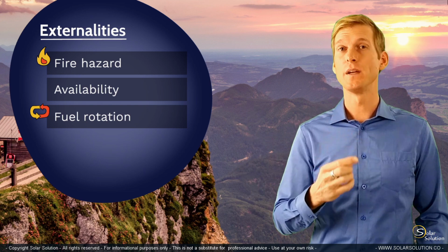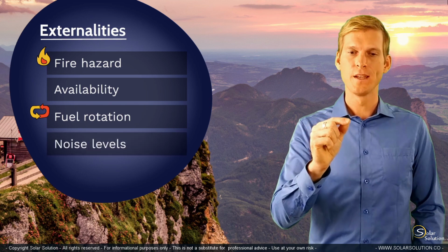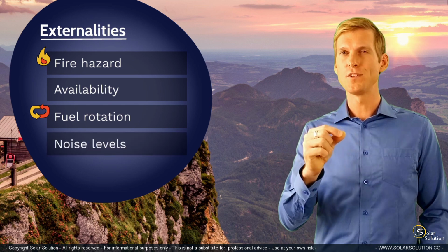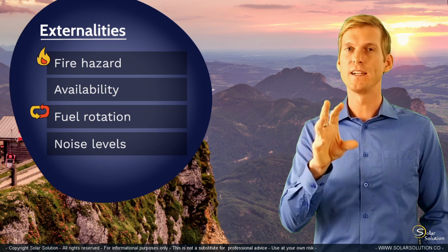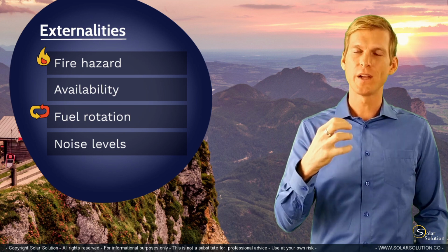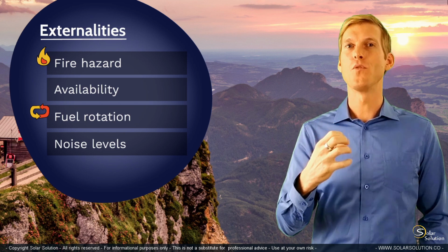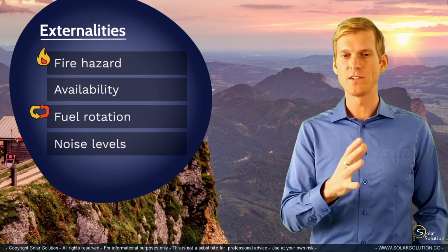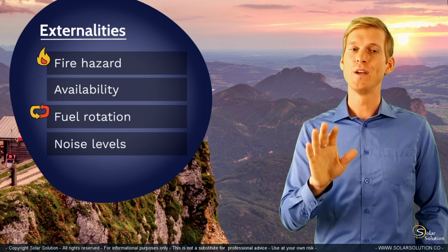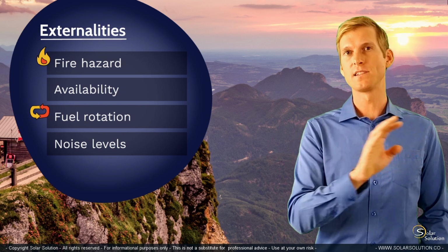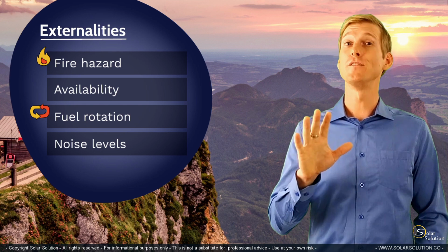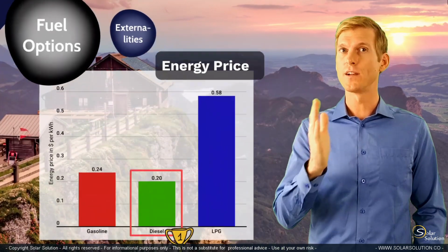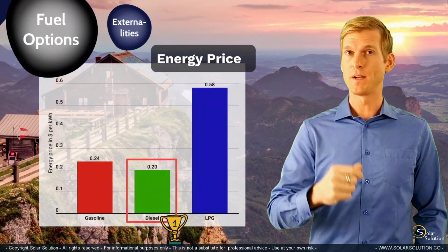And the last one I want to mention is regarding noise levels, because diesel engines work with self-combustion, so they don't have spark plugs that ignite the fuel, and therefore diesel engines are typically way more noisy compared to gasoline engines. So if this is an important factor for you, you might want to stick with gasoline generators. So these are just a few of the externalities that I want to mention regarding the different fuel options that you might want to consider.